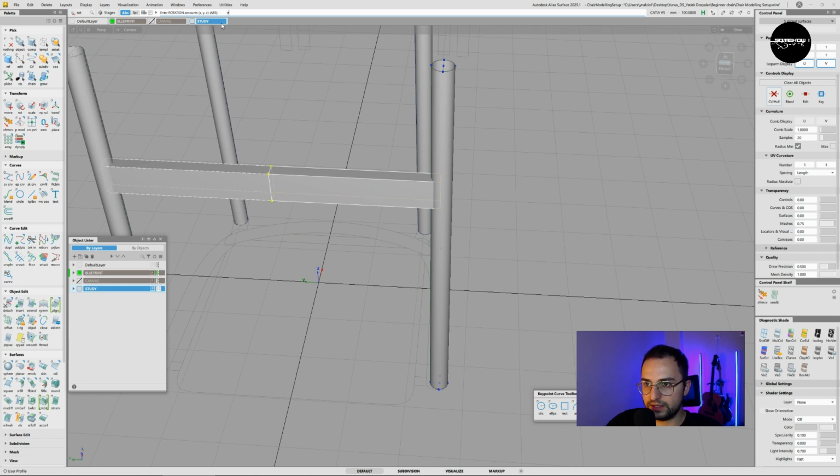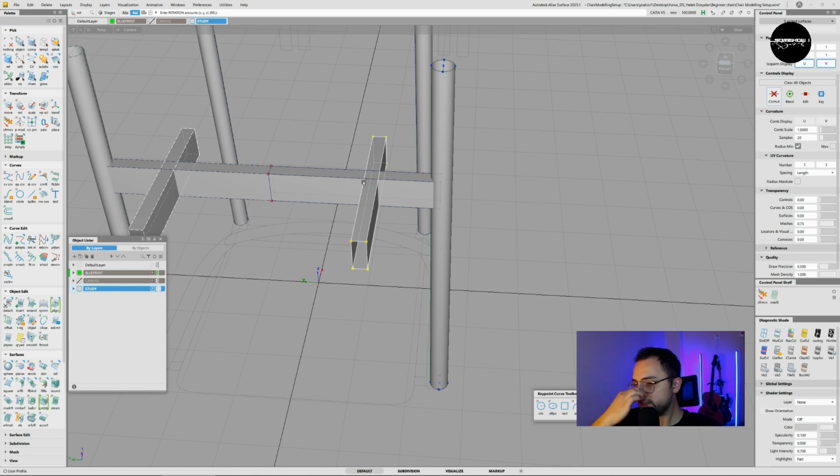If you hit ABS here, it is for absolute, which means it is going to be considering the origin of the grid. But we don't need that. We need relative. Hit R and enter. You see relative. Right now I am gonna use 0, 0, and 90. And this represents X, Y and Z rotation. So I have rotated on the Z axis.